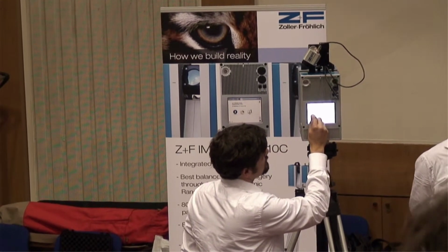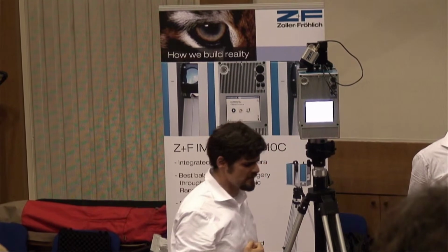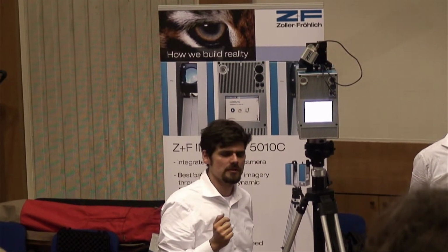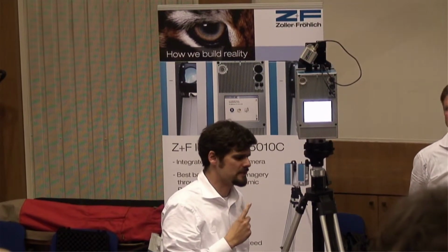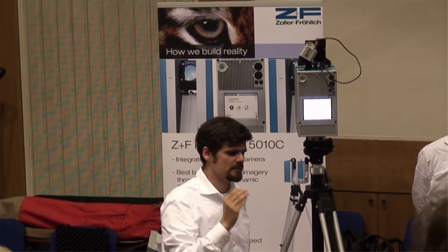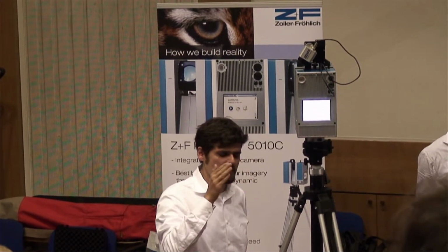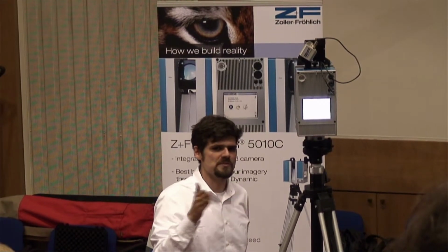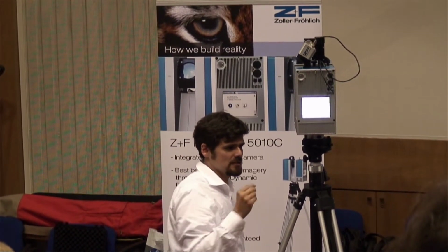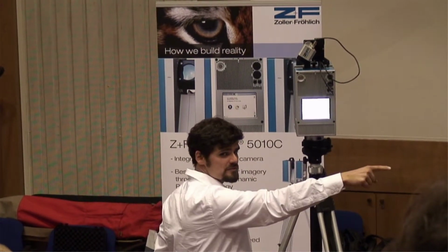Then we've got the quality setting. The quality is basically the speed with which you acquire each point. This is very important to understand, and if you compare scanners, you need to make sure you compare the accuracies at the same measurement speed. Because you can imagine, let's say a scanner has 1 second to measure the distance to one point.